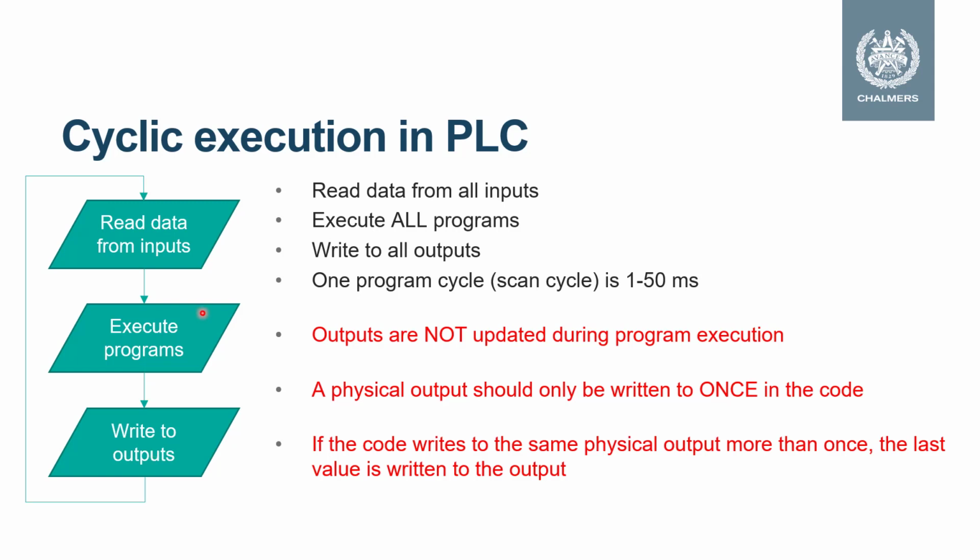The first word of advice: do not write to the same physical output, the output signal from the PLC system, more than once in the code, because the system will only use the last value written to the output.